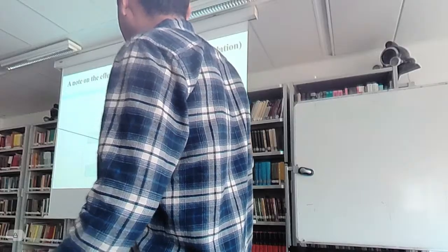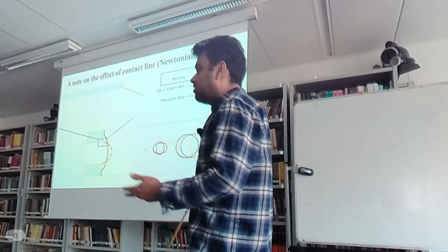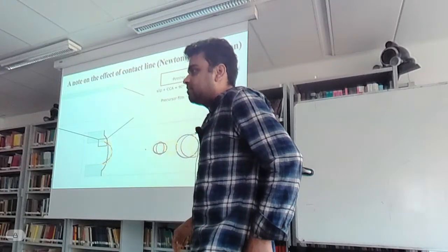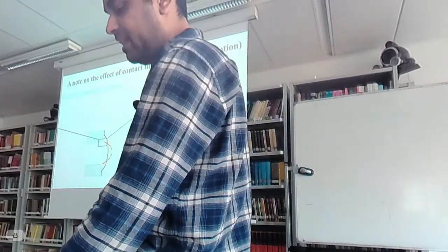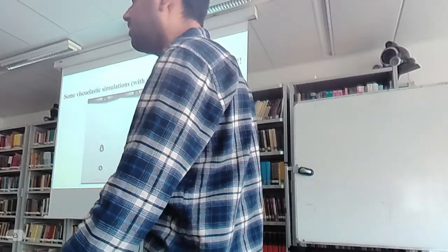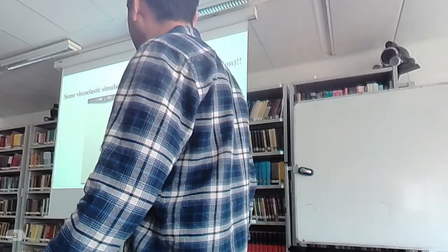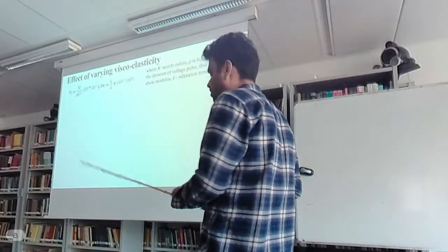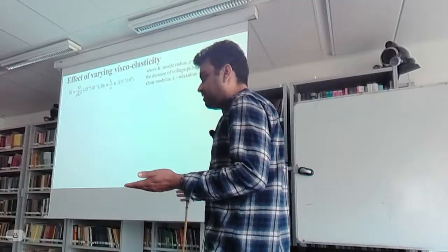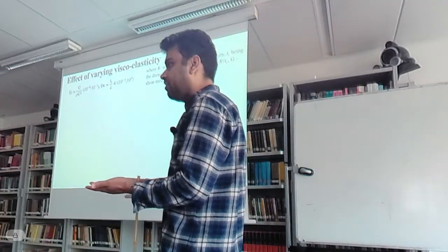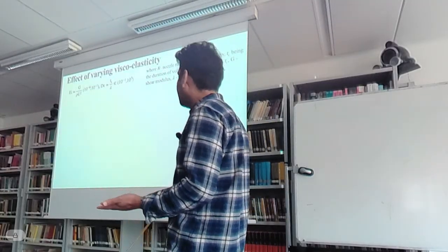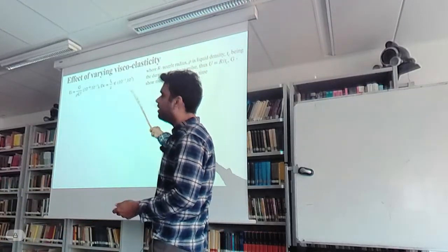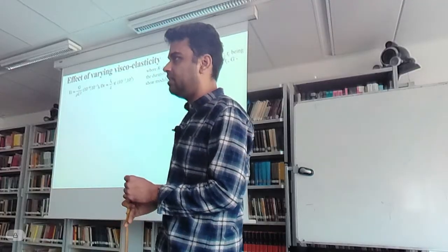And what we do is we still argue that phenomenologically most of the things are similar, and we try to understand the details of the simulations better by using a pinning boundary condition, and try to go back to this situation: can we reproduce this situation in the numerics? And it turns out that, okay, I fix already several parameters like the geometry of the print head, etc., the driving pulse, and what I vary is only the parameters that control the viscoelasticity of the ink.